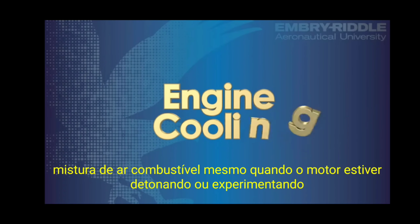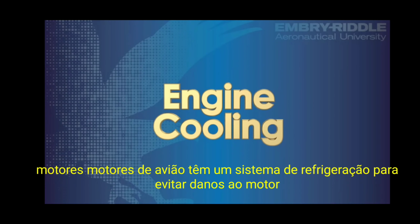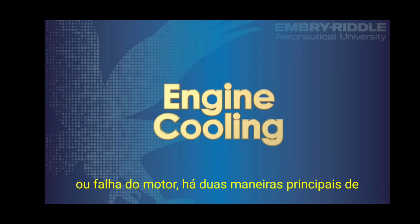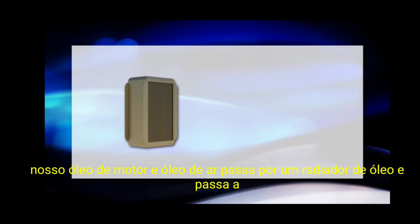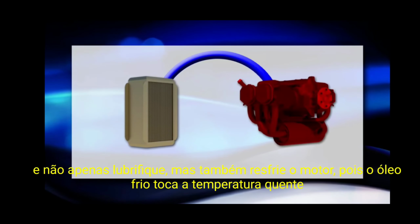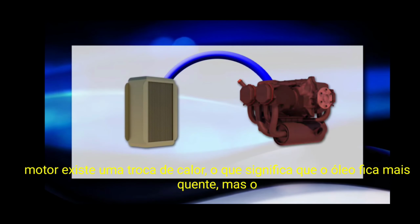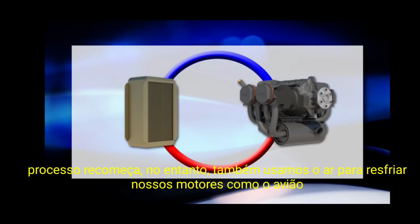Even when the engine isn't detonating or experiencing pre-ignition, the temperature of an engine can get quite hot. Like car engines, airplane engines have a cooling system in order to prevent engine damage or engine failure. There are two major ways we cool our engine: oil and air. Oil passes through an oil cooler and proceeds to not only lubricate, but also cool the engine. As the cool oil touches the hot engine, there is a heat exchange, meaning that the oil becomes warmer, but the engine cooler. Then, the oil returns back to the oil filter and oil cooler, and the process starts over.